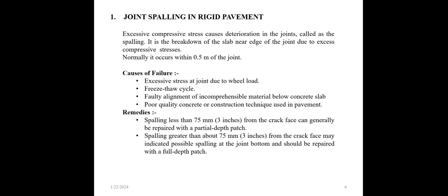Remedies: spalling less than 75 mm (3 inches) from the crack face can generally be repaired with a partial depth patch. Spalling greater than 75 mm (3 inches) from the crack face may indicate possible spalling at the joint bottom and should be repaired with a full depth patch.